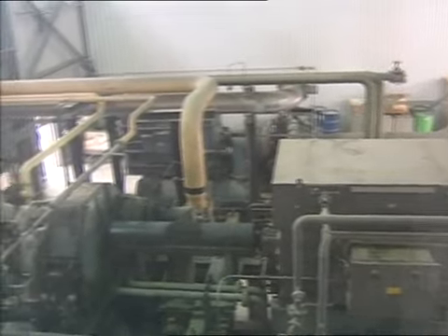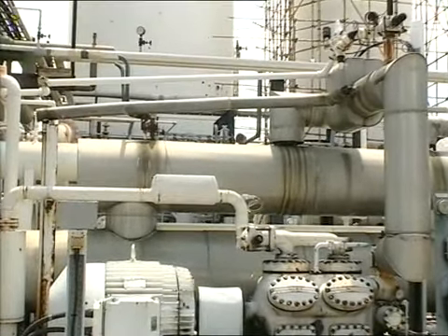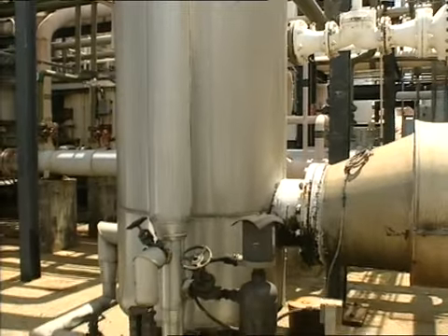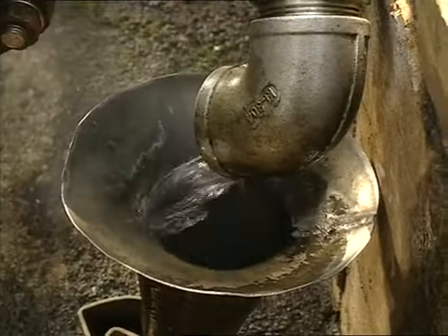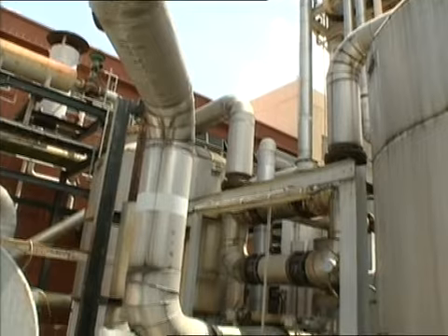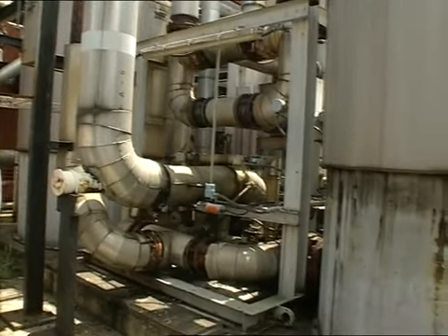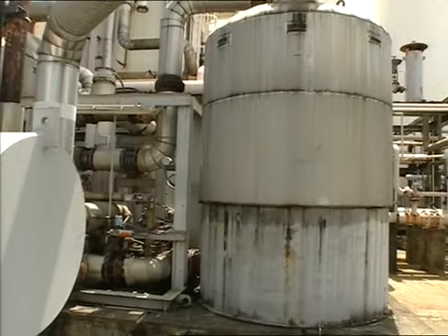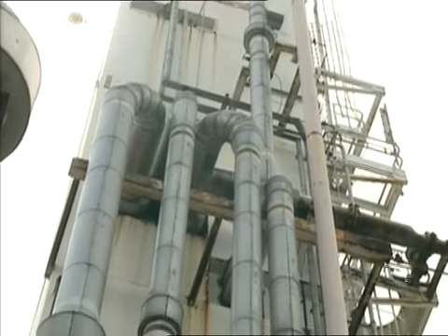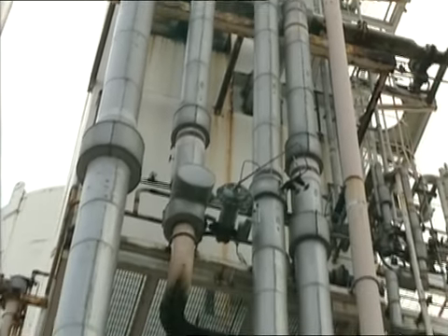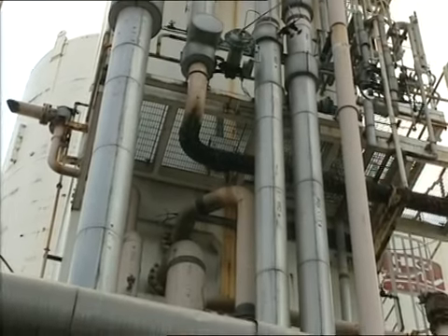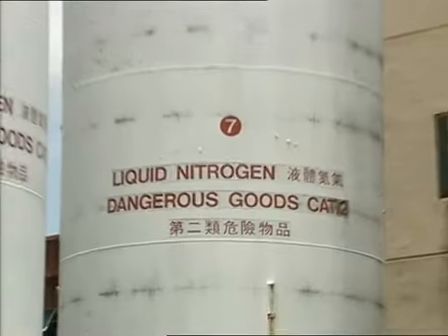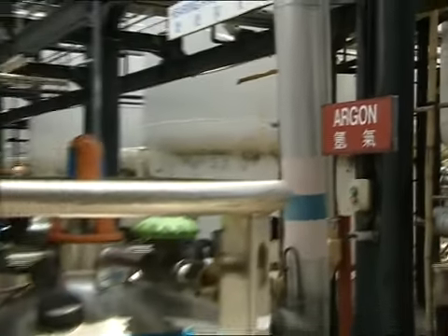After filtering and compressing the air, we feed it into this condenser, where the water in the air condenses and is separated out. Here, we cool the compressed air to about 5 degrees Celsius. By passing it through this dryer, we remove the minute amounts of carbon dioxide. The air then goes into this freezer, where it is cooled to approximately minus 107 degrees Celsius. From there, it is fed into the fractioning tower, where liquid oxygen, nitrogen, and argon can be obtained at different temperatures.